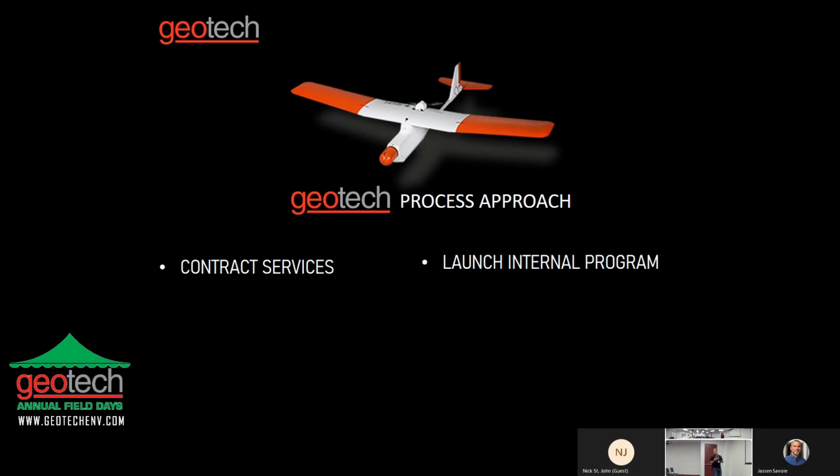So it's the right tool for the job, to conclude on your question. Depending on the size and scope of the project, we manufacture a multi-rotor, 2 fixed wings, and a helicopter that we sell and also pilot. We'll figure out what payload you need, because the helicopter carries heavier payloads than the fixed wings. So if we need LiDAR and dual camera imagery, we're going to take the helicopter out on site.